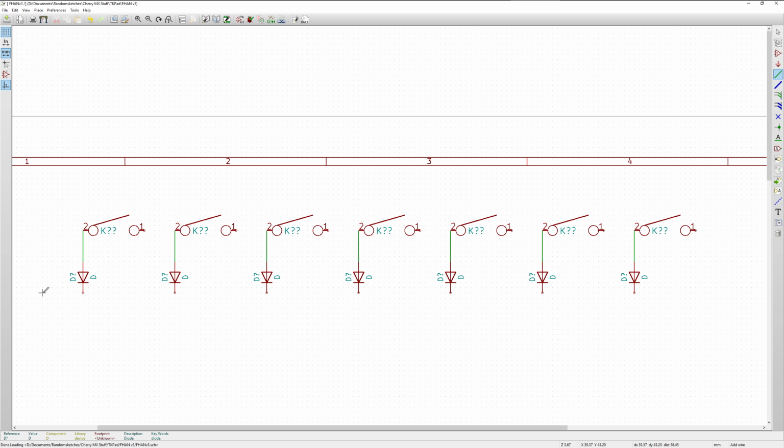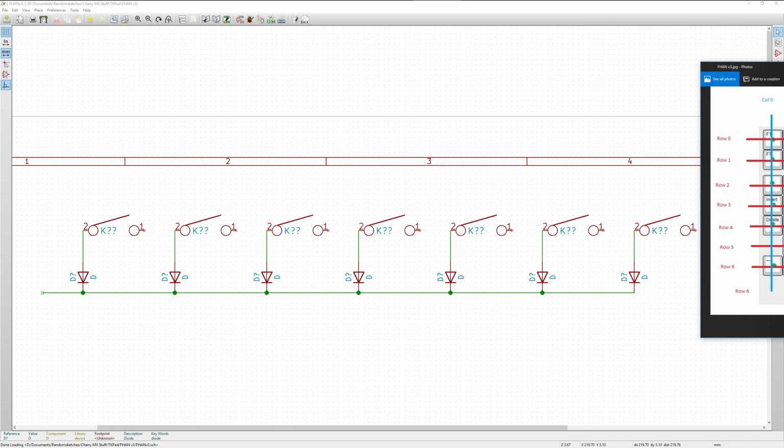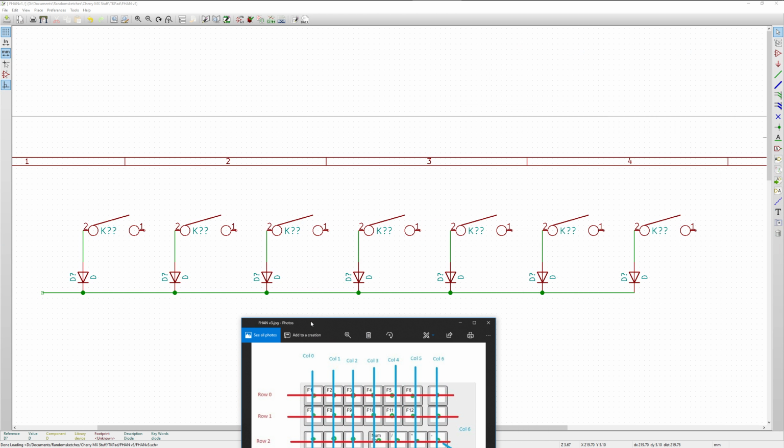And what I'm going to do is I'm going to run a wire across that entire row. And you'll notice that when I do these joins, I'm not running it right across as one line. The reason is because if you run across one line and you don't get these circular dots, you might miss the fact that they actually have a connection there. The circular dots, at least on a Y junction, is always good to have to ensure that you get that connectivity that you want. Now I'm just going to drag this back over so we can see what's happening here. So this key should be F1, F2, F3, F4, F5, F6, and this last one is our first customizable on column 6.